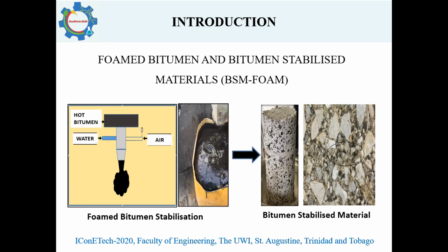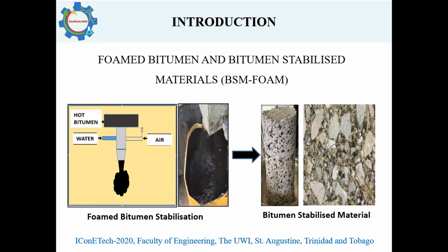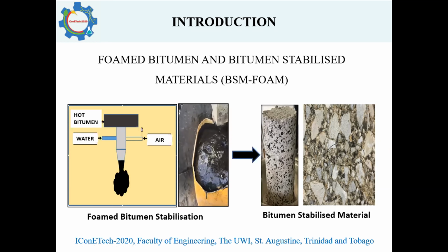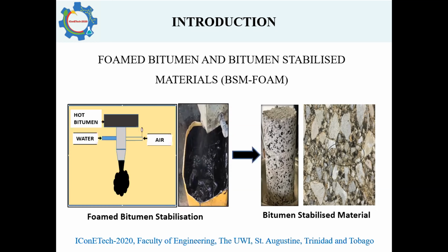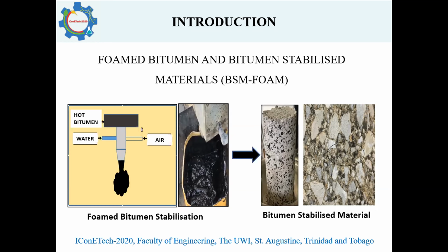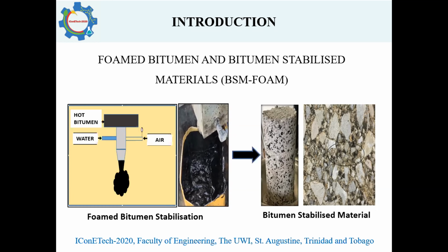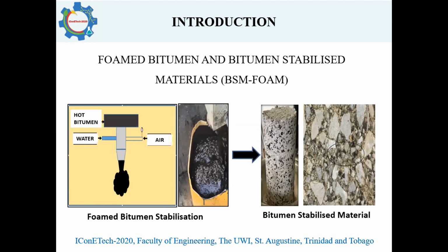When mixed with the parent material aggregates, the increased surface area from temporary expansion allows for the coating of the finer particles within the aggregate skeleton. Upon compaction of this material, the bituminous mastic produced between the fine particles and the foam bitumen is described as conceptually spot welding the coarse, uncoated aggregate materials within the aggregate skeleton.